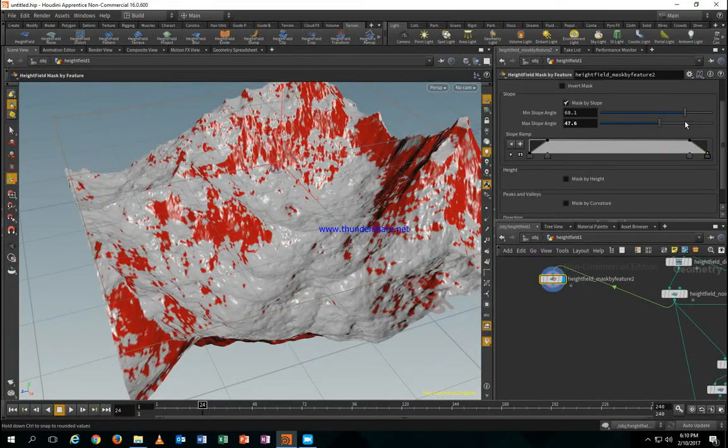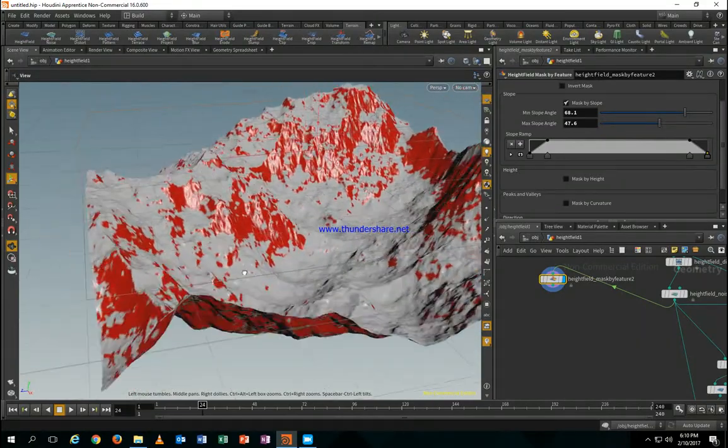What you say, you want the higher slopes to get masked. Actually, my problem was that when I tessellated my HeightField, since I have limited processing power, my HeightField, whatever its resolution is, the tessellated mesh after that has jagged edges where the edges are sharp angles. Ah, I see. Because everywhere else I don't need that much resolution, but where I got a cliff with a 90-degree angle, I need a lot more resolution in this place. I see what you mean. Is there a way to tessellate it more in those regions?